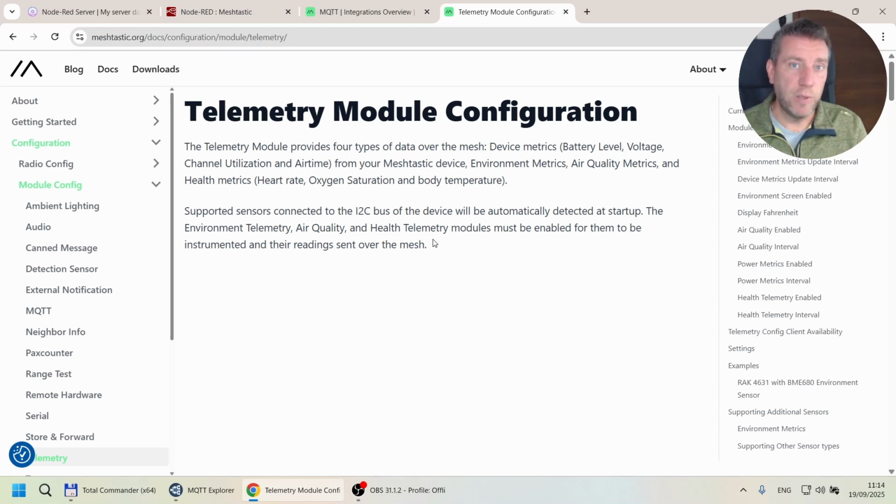So the one example is that you have, let's say, an ESP based chip, which is running Meshtastic. And then you have a second microcontroller which is connected to some sensors, and the two microcontrollers are connected together, because in Meshtastic you can connect a separate microcontroller to the main microcontroller, and then it would be able to relay messages back and forth between them.